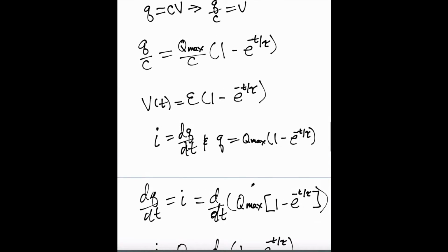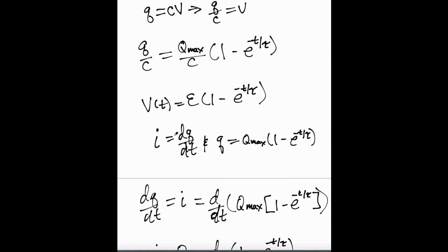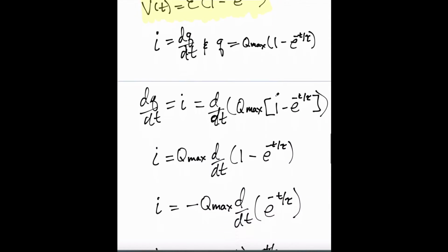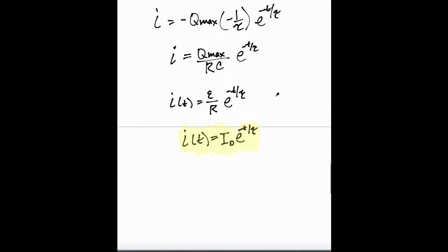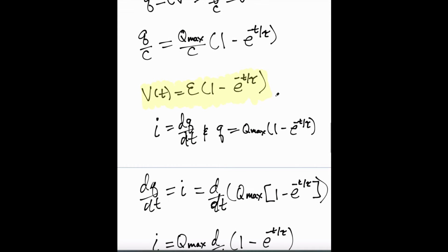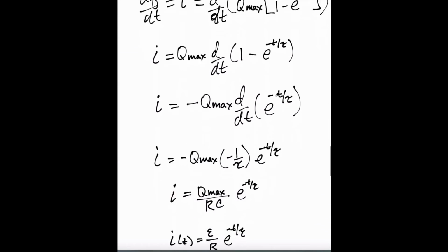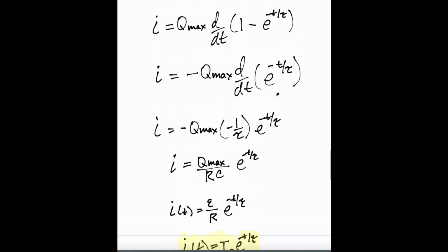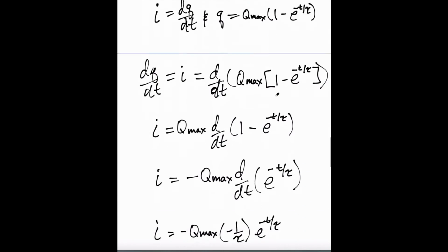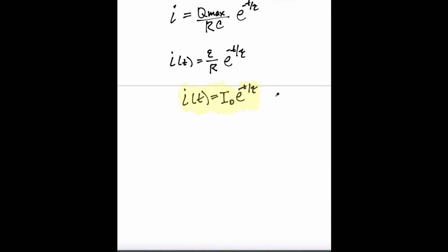We forgot, by the way, to highlight this expression, and I like highlighting. So we actually found 3 different expressions here using the separation of variables and differential equation stuff. We found charge as a function of time in the capacitor, voltage as a function of time in the capacitor, and the current as a function of time for the capacitor. And both current and voltage are fairly straightforward to measure in a circuit when you build it yourself, especially if you have a microcontroller like an Arduino, whereas charge may be harder to actually find in most scenarios. All right, there you go.